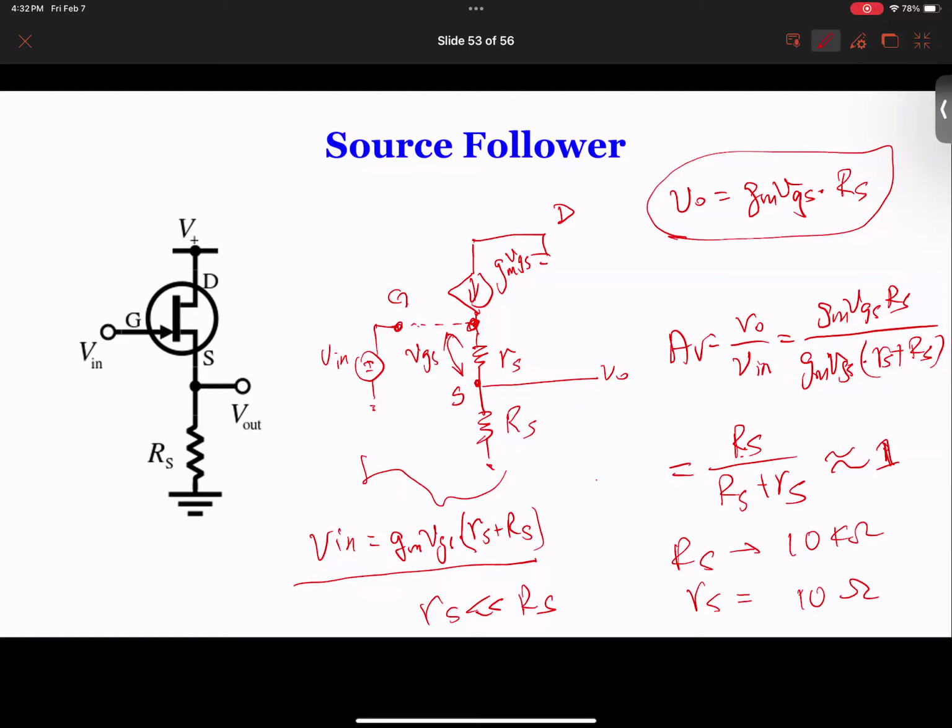Because the gain is almost 1, which means the output is almost the same as input, right? Because gain is 1, so output is the same as input, which means the output over here is almost the same as here. The reason is because the voltage drop over here is very small. So for that reason, we call this a source follower, which means the source is following the gate. Basically, whatever you apply to the gate, you get almost the same output, sometimes 0.998 or 0.997. So it's very much the same as the input. So this is why it's called a source follower.